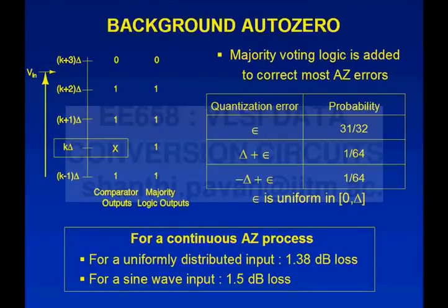Let's assume that a comparator far away from the input is being AUTOZEROed. So the output of this comparator: if this is being AUTOZEROed, the preamp is being pulled out and the latch makes some random decision. So it could be either a 1 or a 0. If this was a 1, then there is no problem at all, right? Because this is still a nice thermometer code and there is no issue. If on the other hand this turned out to be a 0, you know that this is a spurious thing, correct? This is like a so-called bubble in the thermometer code.